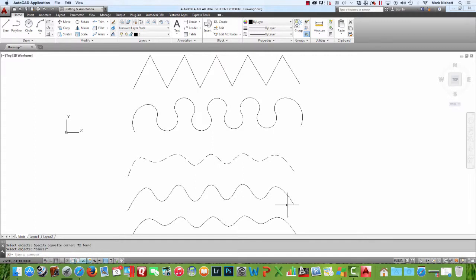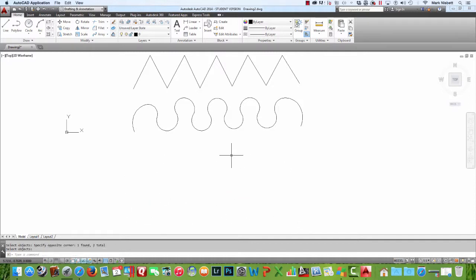So that's why if you're ever working on a contour plan on a topography map and you explode a polyline on there, your drawing ends up becoming really huge. There's a variable that controls this. By default, the spline, or what they call spline edges, is set to 8 segments in between these.